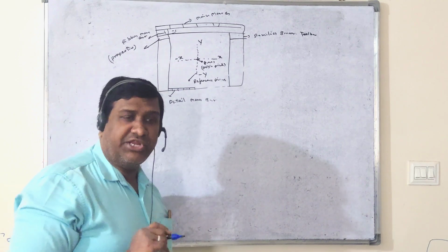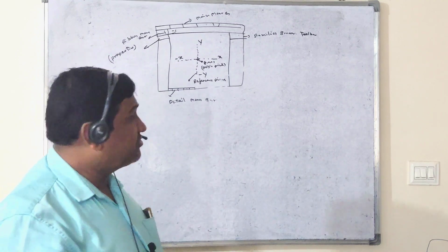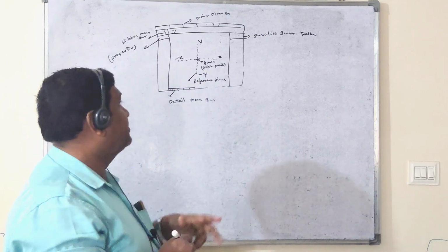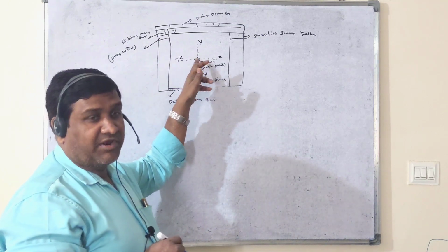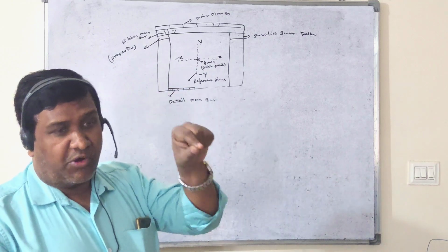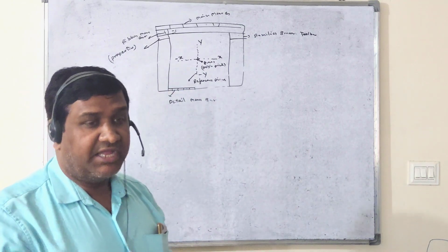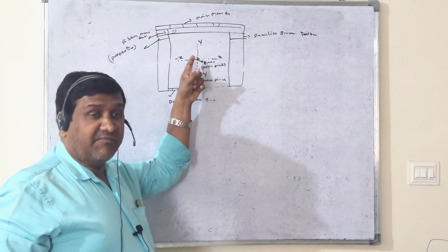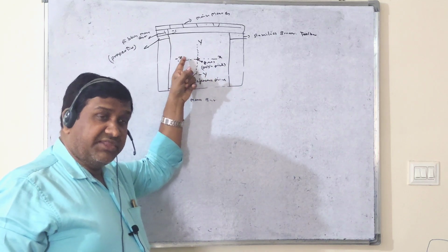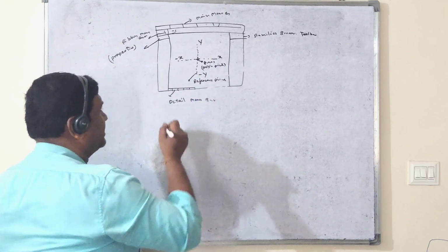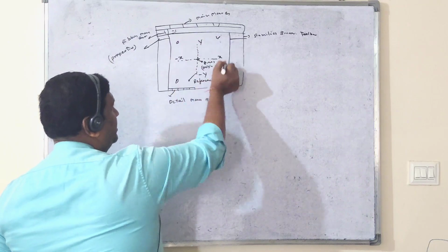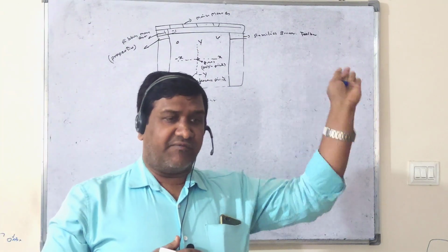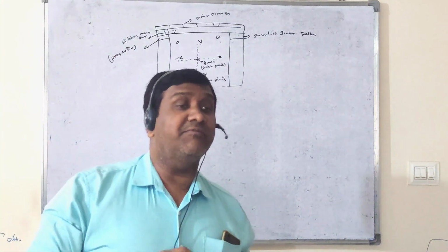So whenever you create any family, you have to start with this reference plane only, from 0. At the point where the planes intersect, where there is a perpendicular point, you have to start the family creation with the help of this origin only. Don't create here, don't create here, don't create here. Some people create the reference plane somewhere, but do the family creation somewhere else.